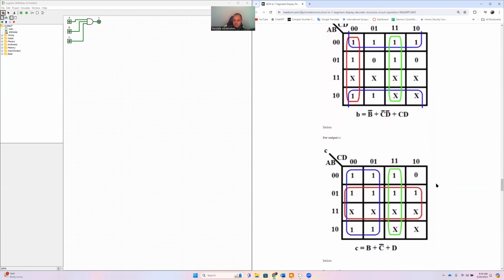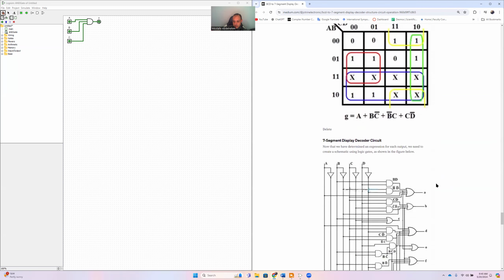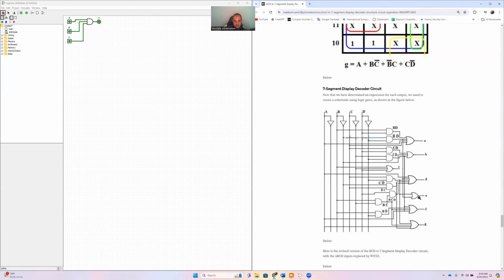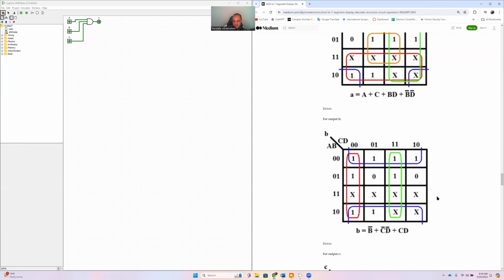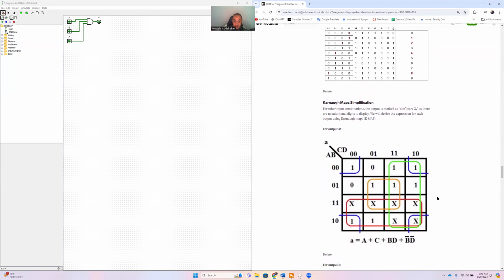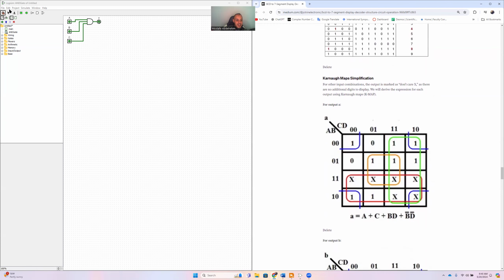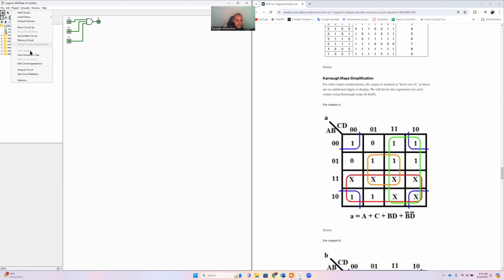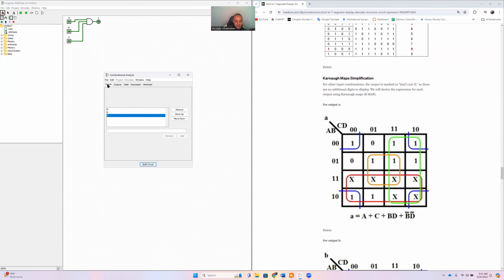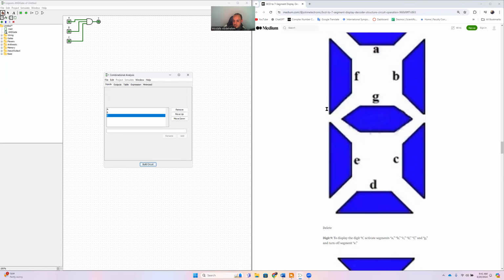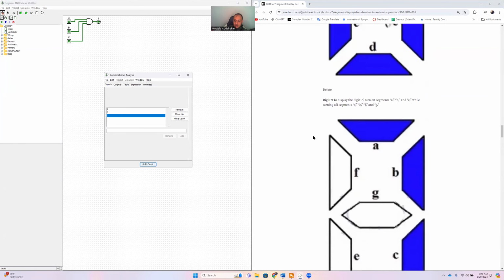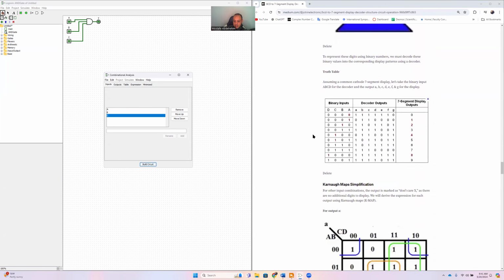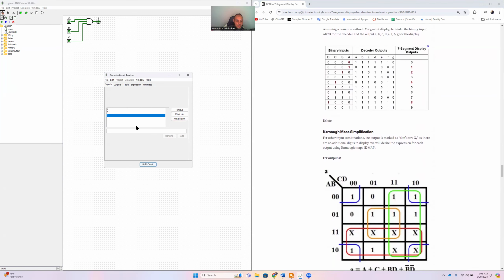So you're gonna have to do this 7 times, as we mentioned, and this will be the circuit at the end. So how can we do this? Very simply, using Logisim in like 1 minute. Okay, so let's see. Again, we're gonna go to Project, then Analyze Circuit. Inputs: we have 4 inputs, so let's add another one. Let's call them ABCD. Okay, yeah, ABCD.